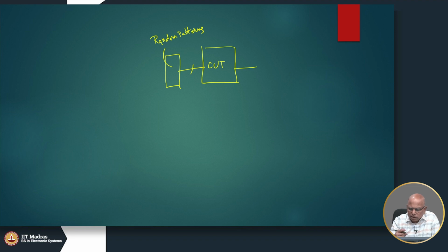If random patterns are unable to detect all the faults, okay, so let us say random patterns give 80% coverage. For the remaining 20%, we may still need ATPG. See, this is a bad thing. So, we may never have a perfect solution where it is fully self testable, right? Meaning it is fully capable of generating all the tests by itself. So, this is called as top up patterns.